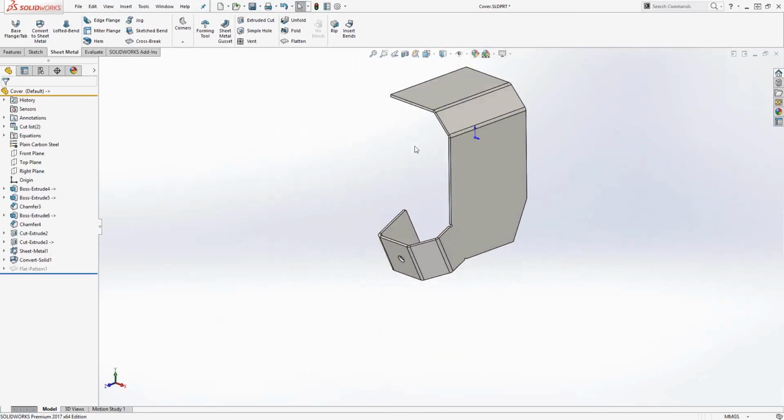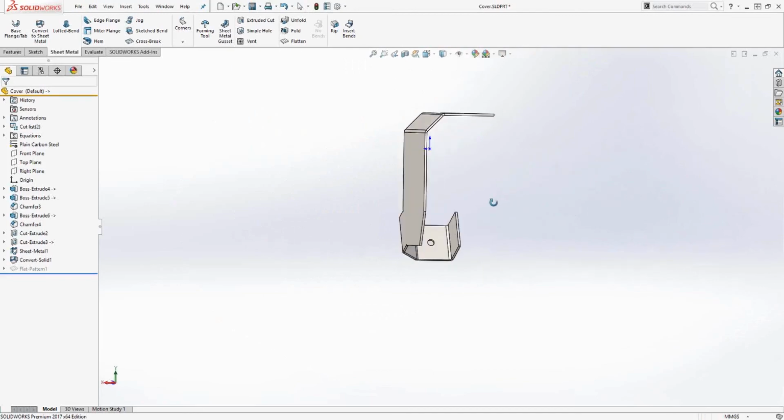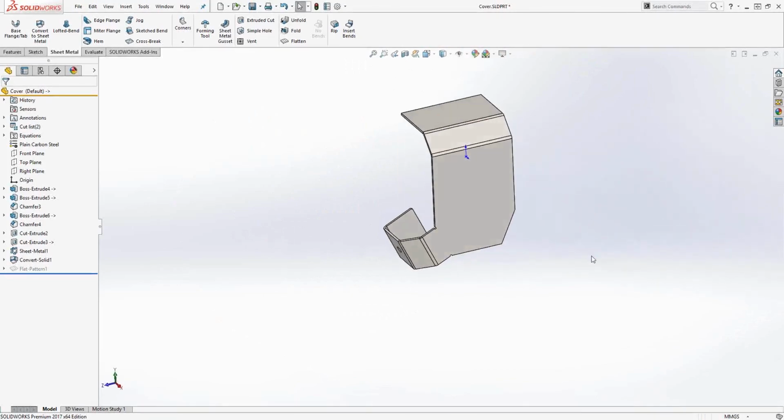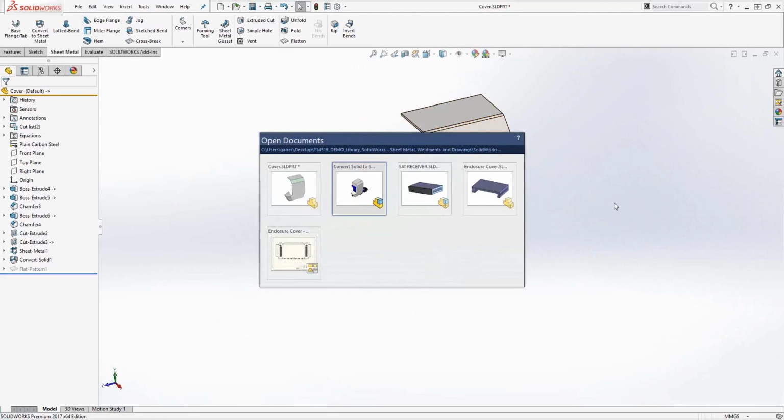You can do that very quickly and adjust those parameters however you see fit to create that kind of sheet metal enclosure or a guard or cover for things very quickly by just, again, starting with a solid body, and then you're wrapping a piece of sheet metal around it, selecting the edges to create those bends like that. Okay.